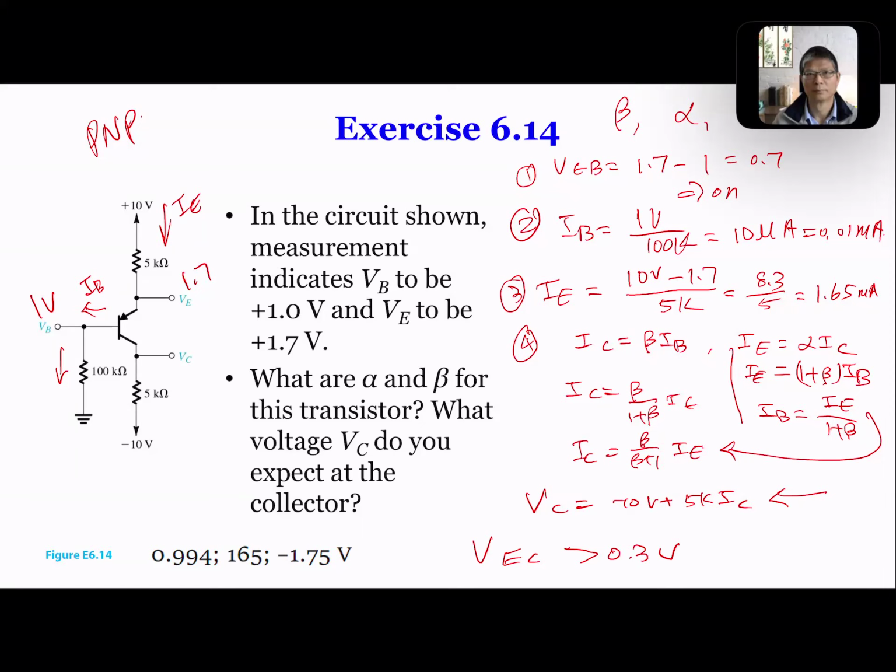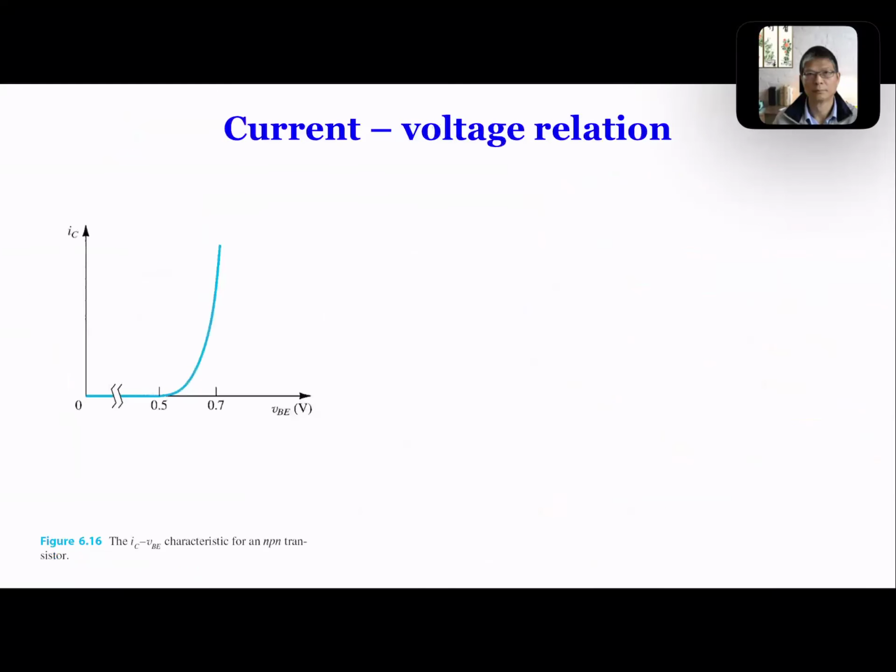But in the BJT, the region where the current is flat is called active mode. The current is not flat, but changing, that's an area called saturation. So even though they both call it saturation, they're really referring to different operating conditions, and that is inherited from the original behavior of these devices, and that's just how it happened.